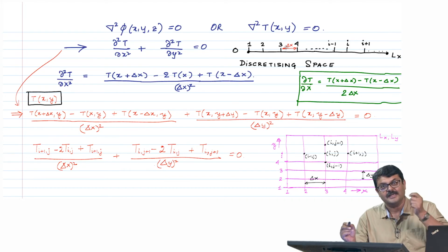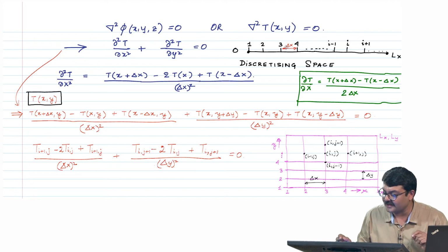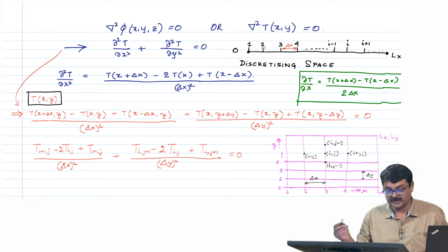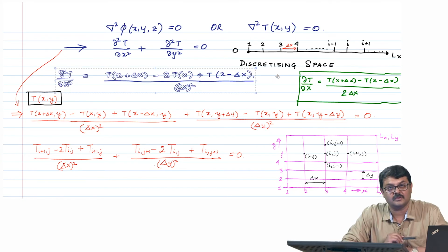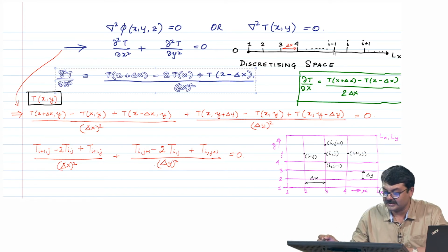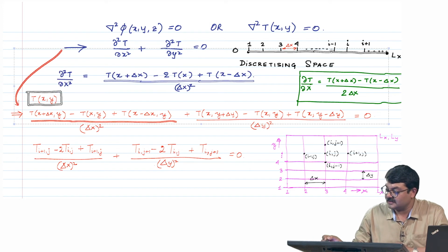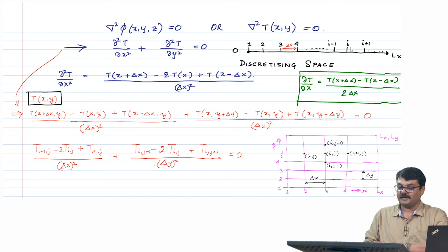So, you are calculating temperature at discrete points of space separated by delta x, and the distance between 1 and 2 is delta x, and this is how you can write down the second derivative. Basically, you are calculating the temperature at x plus delta x, like i plus 1, this would be the temperature at x minus delta x, and this is the temperature at x, right.